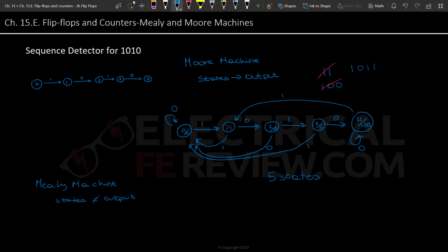We basically need the number of bits in the sequence and a state 0. To create a desired output where a light only switches on when it reaches a full sequence, we can say that the most significant bit is the one determining whether we get to the 4th state or not. So we just take into account this bit.